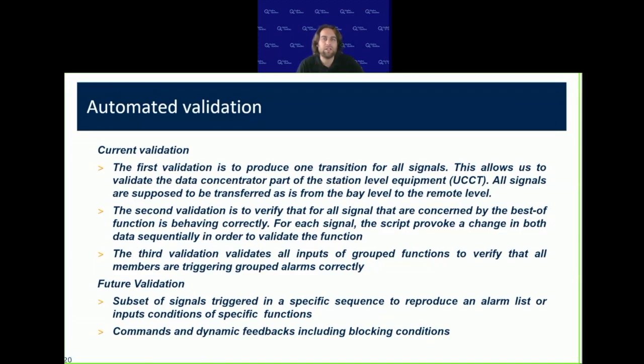We're also aiming to validate all the commands, as much from the remote as from the local HMI, by testing all the blocking functions every time and making sure that the system responds well in all functions. What is very important here and very practical is that the model is predictable. Based on the SCD file that we have for the station, it's possible to extract all those signals automatically. So we don't need to define what we will test. We base it on the SCD that's been generated from the common data model. And that is really the power of this model that we have.